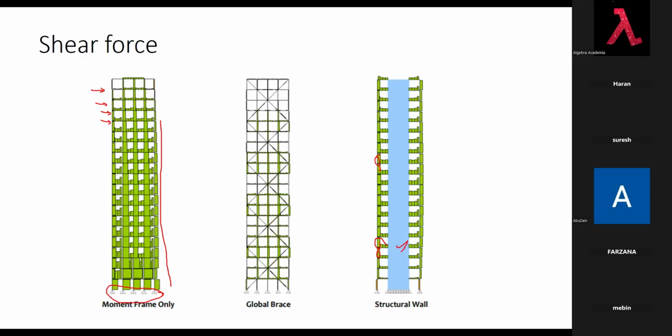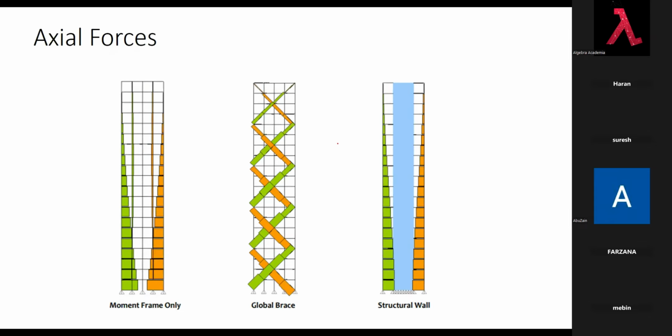The shear forces we see here are all developed due to the individual mass. Each column will be associated with an individual effective mass. This mass will generate the horizontal force. Now the axial force, the same problem. Axial force is the main thing for column design. As you see in the moment resisting frame, the ground story column has to be designed for heavy axial load. In case of shear wall system also, we need to design for it, because